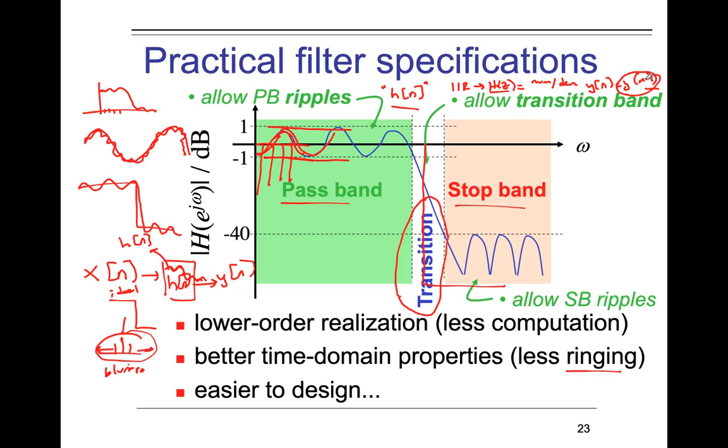So in terms of H of n, I cannot write immediately the H of n. I cannot plot H of n immediately, just as I have done with FIR filters. But you have to think in terms of, here we have a feedback, and we have both y of n and x of n in our discrete difference equation, okay?